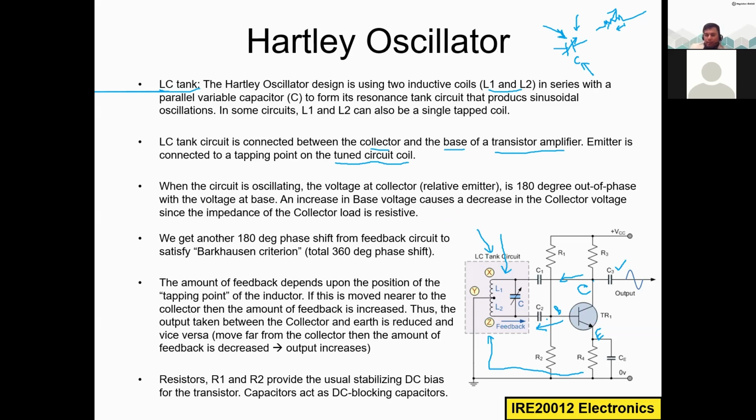So what does it mean? I increase the voltage at the base, then what's happening? It means I am turning on this transistor, so the transistor will be in the on mode. It means I am short circuiting this collector and emitter, so current conduction is happening rapidly between the collector and emitter. So I increase this base voltage, then because of this short circuit, whatever voltage is present here will get reduced, because this will just go down.